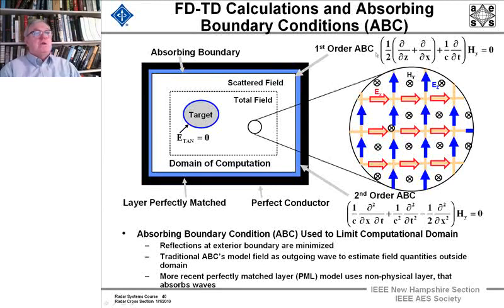And so there are certain absorbing boundary conditions, a first-order absorbing boundary condition at the edge of this absorbing boundary, which is this differential equation, and also at the boundary between a perfect conductor and the absorbing boundary, we can put a second-order absorbing boundary condition.